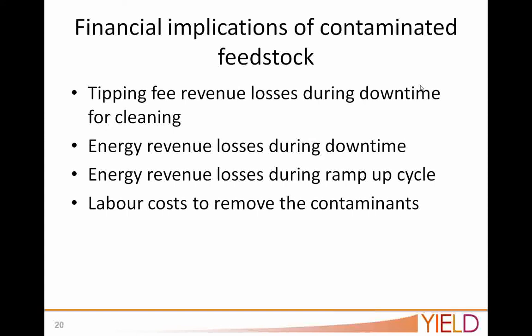Plus, you've got the labor costs associated with removing the contaminants from the tanks. You have to get people in the digester. It's not cheap. You can't empty it 100%, and you need vacuum trucks or pump trucks to get the material out. People have to get into this environment. There's still hydrogen sulfide being produced, so the labor costs can be a lot greater than people really think at the end of the day, and it generally takes longer.